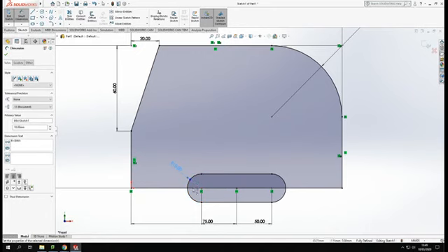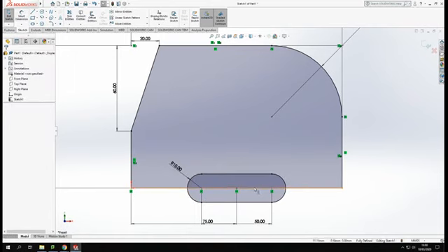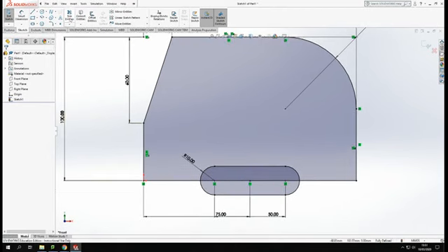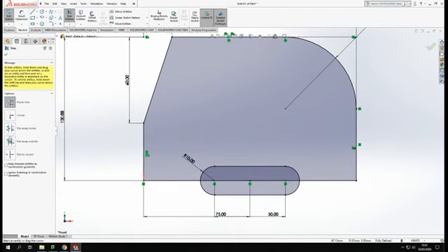However, with that, all I actually want to use to make this component shape is this upper section. So I've got a lot of extra drawings in here that I didn't want. So if we go to the trim tool here, we've got a few different options that we can use. So we've got a power trim, which is where we just slide a line through it and it gets rid of it. We've got corner trims where we can trim off to a corner. So if we've got lines that cross over. We've got trim away inside. So if we've got multiple lines that cross over inside a sketch, we can use that.